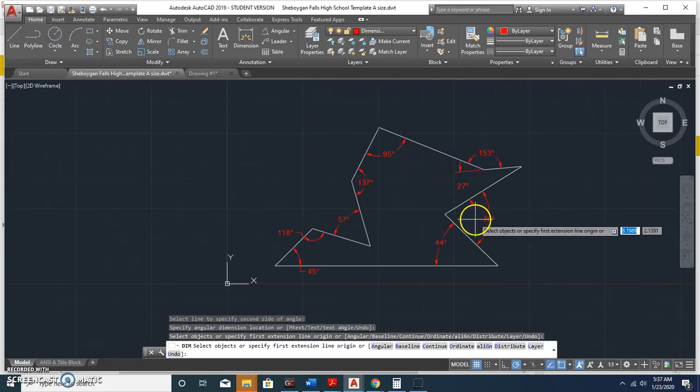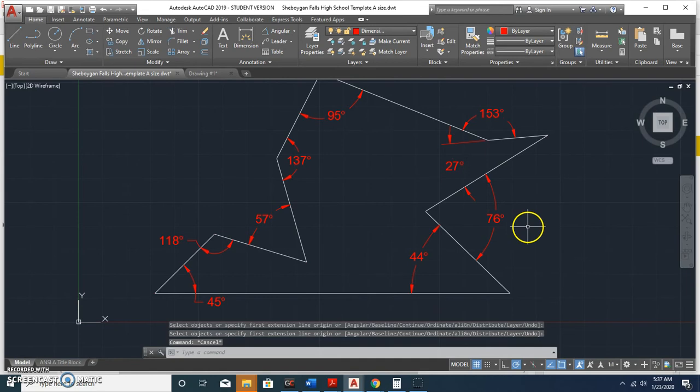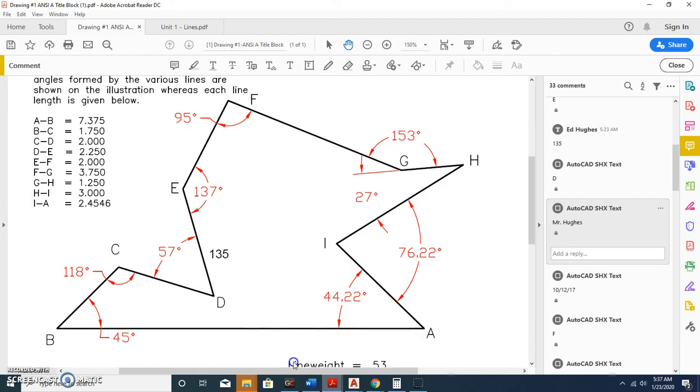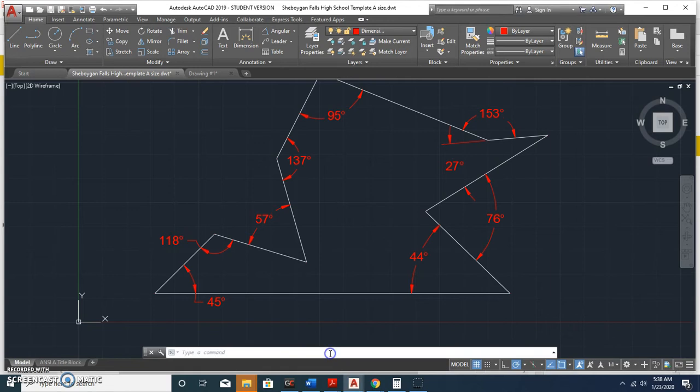Okay. All right. Now, basically I went through and placed all those dimensions. Now you should notice something: two of my dimensions are carried out to the second decimal place. I just put that in there to make sure that all your geometry is correct, but you need to set that annotation to those two decimal places. So how we do that, I'm going to select both. I'm going to make both of these active, so I have them selected.